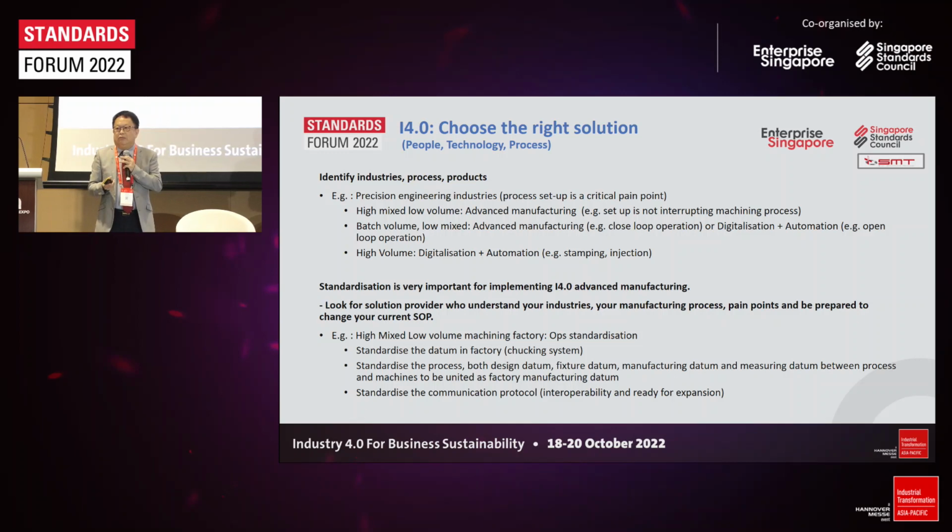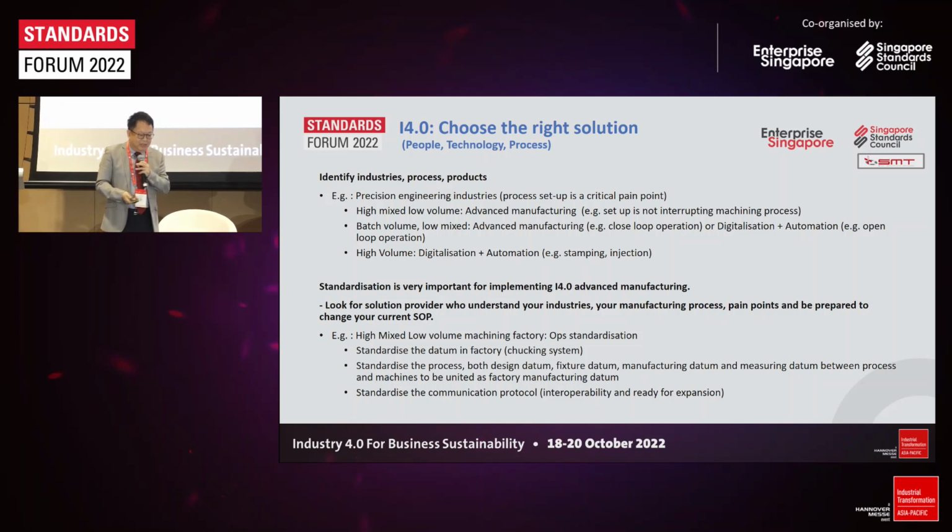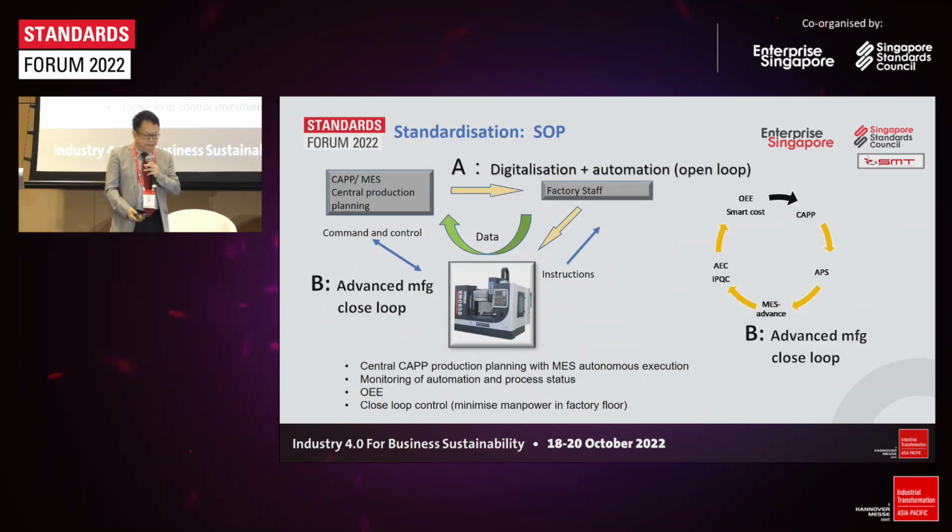In precision engineering, we all know you want to maintain accuracy. Normally, when you put a part onto a machine, you try not to transfer it to another machine. You want to finish all the processes in one machine. But once you unite this datum, you are able to do transfers and tap on the advantage of the different capabilities of different machines. Another standard is the communication protocol. So SSC, Singapore Standard, we have come out with some standard data that I will share with you.